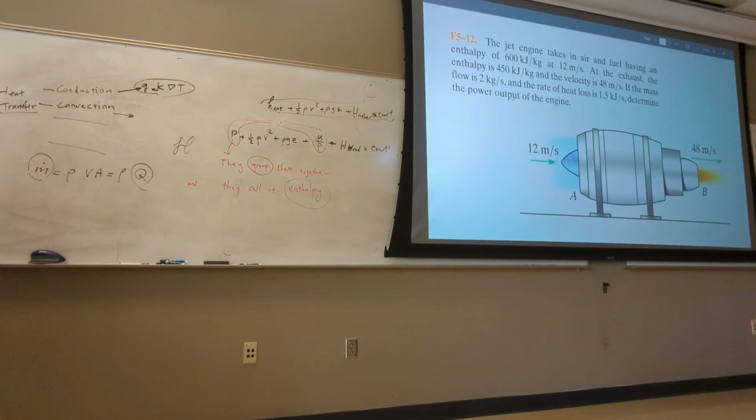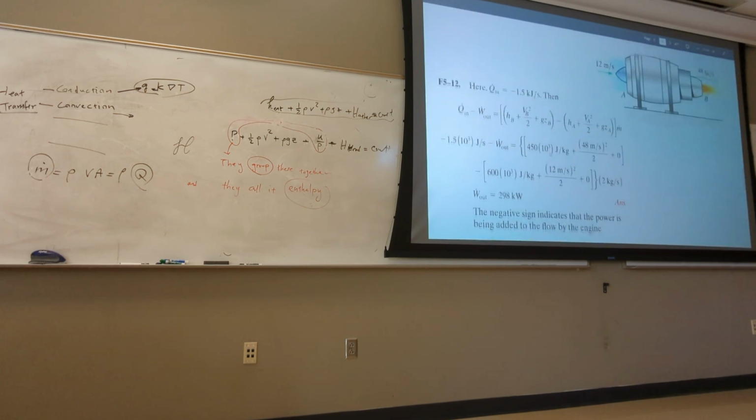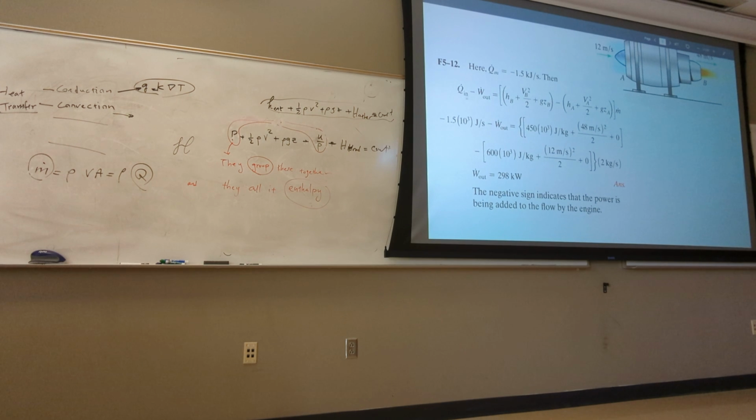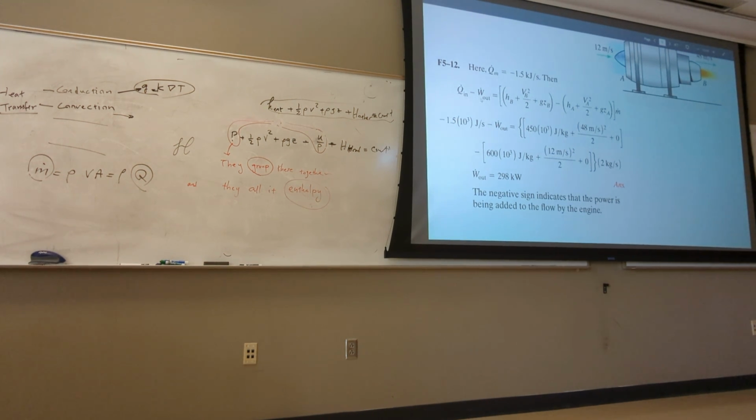So, when you substitute the formula, you got to know what type of nature you have. If you have pump, you have turbine, you substitute that. Now, here, that's the equation we had, Q dot, W dot out, and then these are the head. Look at here, there is no pressure. Do you see that? He regrouped pressure, he grouped it to internal energy, enthalpy.